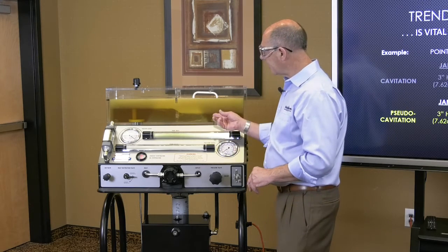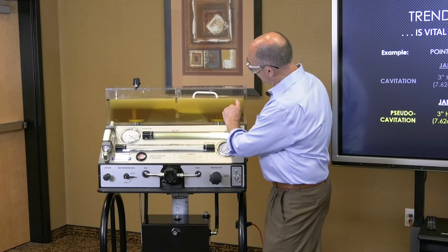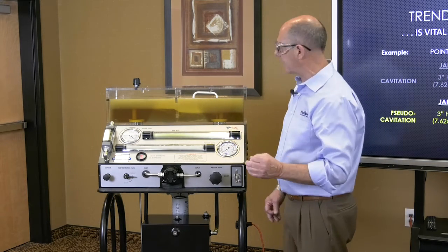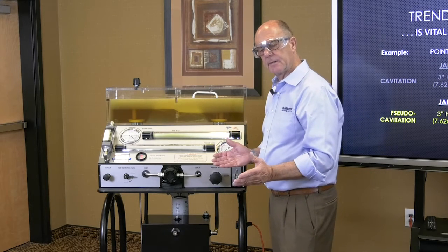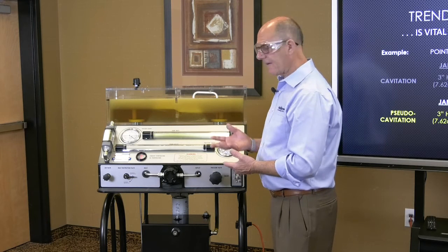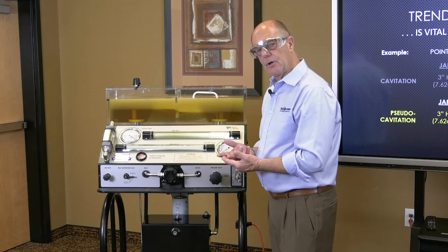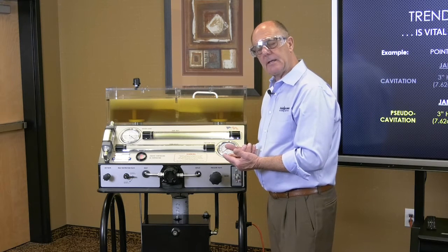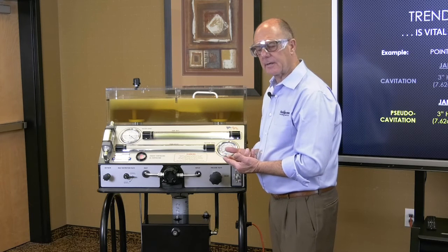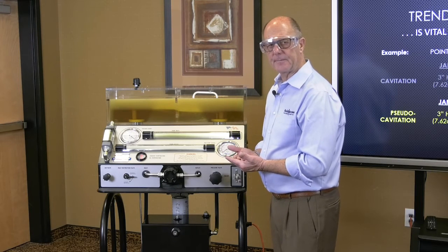However, as you can see here, pseudo-cavitation or aeration has aerated the oil. In other words, what you're seeing in this reservoir is representative of the oil throughout the hydraulic system. So once again, I cannot transmit power with foam. I cannot seal clearances with foam. I cannot lubricate with foam. I cannot carry heat away with foam. This is a systemic catastrophic condition that needs to be nipped in the bud to prevent widespread failure.